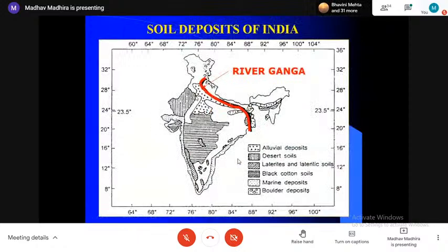Some of the interesting problems I found were collapsible soils here. When you saturate them, they collapse. This inorganic alluvium is a very, very broad term. If you say it's one type of soil, you're mistaken. The only thing is all the soils have been transported from the Himalaya by the glaciers and the rivers, the rivers coming from the melted glaciers.